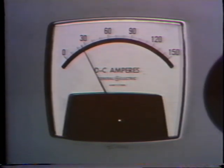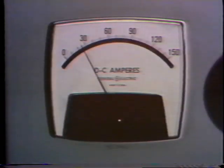This meter on the charger shows you the amount of current in amps that the charger is putting out. In most plants, the battery charger also supplies current to some control and indicating systems that are connected in parallel with the battery. If the plant loses AC power, the battery charger stops working, but the control and indicating systems continue to operate on power supplied by the battery. So the amp reading on the charger meter shows the amount of current being supplied to the control and indicating systems as well as to the battery.